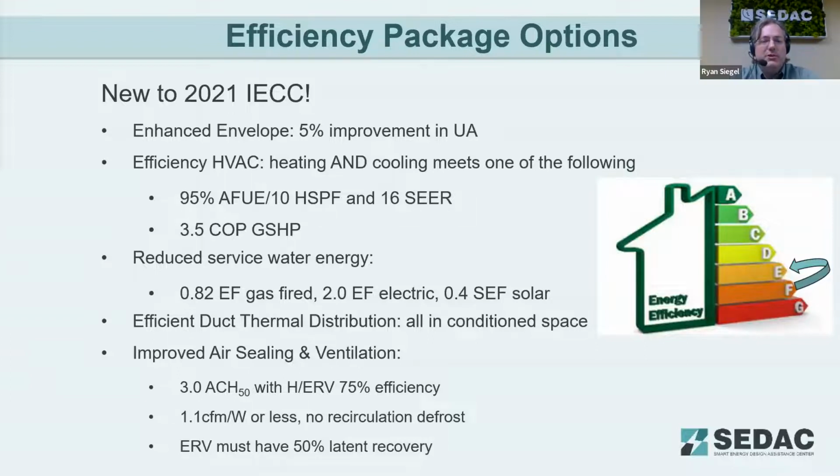What some of these efficiency packages are: improving your building envelope an extra 5%, higher efficiency HVAC, reduced service water heating energy, making sure that you have efficient thermal duct distribution, and potentially better air sealing, along with a dedicated ventilation system.